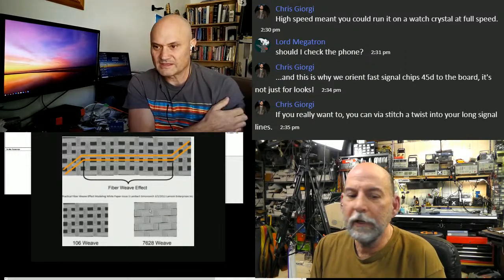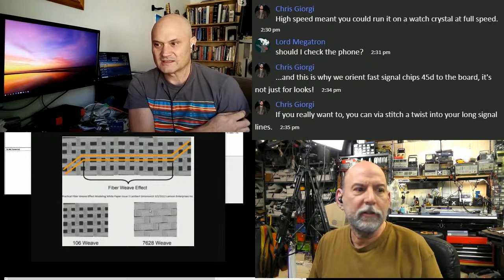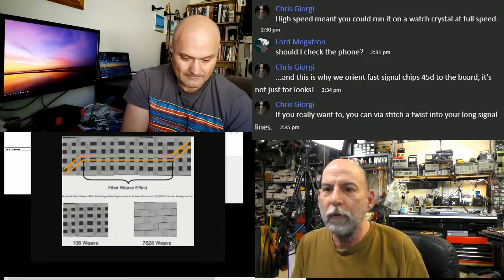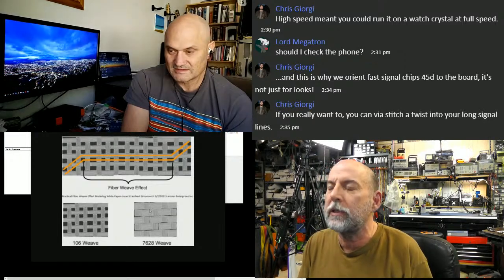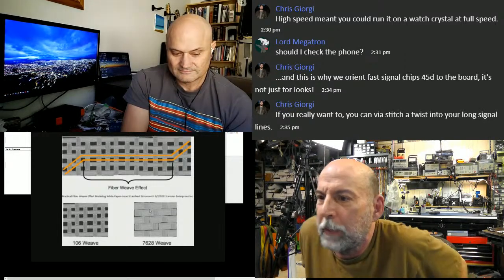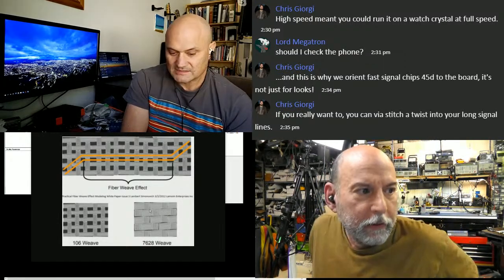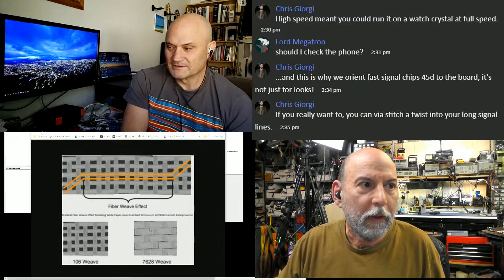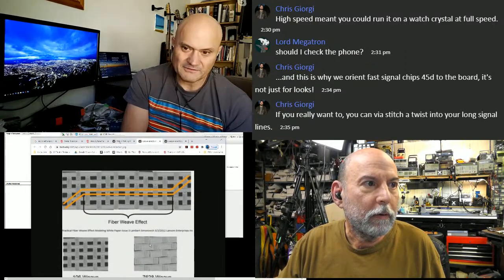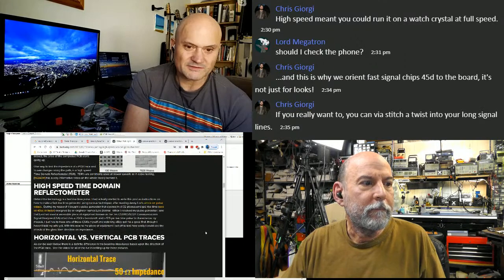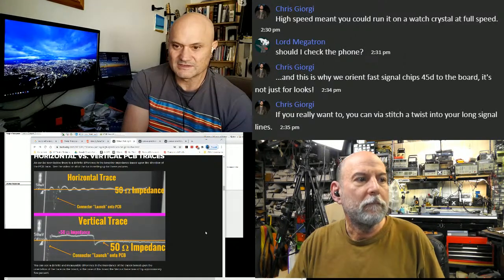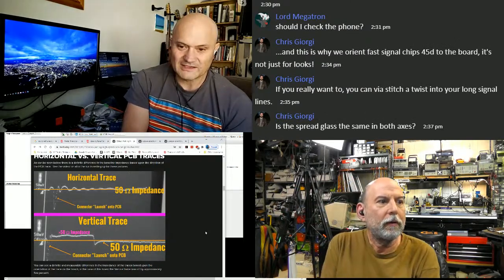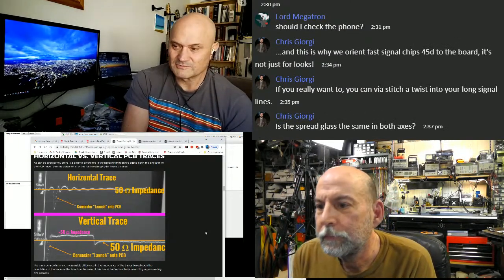I was going to say, yeah, it always helps to ask the PC board house, because if I show up going, oh, I want this fancy weave, they may go, one, you don't need it. Two, we use tons of this other stuff, so it's cheaper and even maybe better. Yeah. So I always ask the PCB fab. Be practical and realistic. If you're talking about differential pairs that are dealing with signal rates in the hundreds of megahertz, you just specify good material, and you probably don't need more.